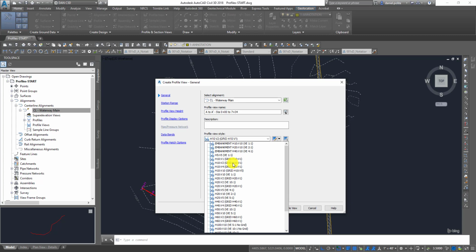You put all this time and effort into drawing things and it never fits on there. So my recommendation is take an engineering scale, figure out what's going to fit on your layout. And it's always good practice to create those viewports right away and put them in your page setup, and that way you know exactly what's going on.